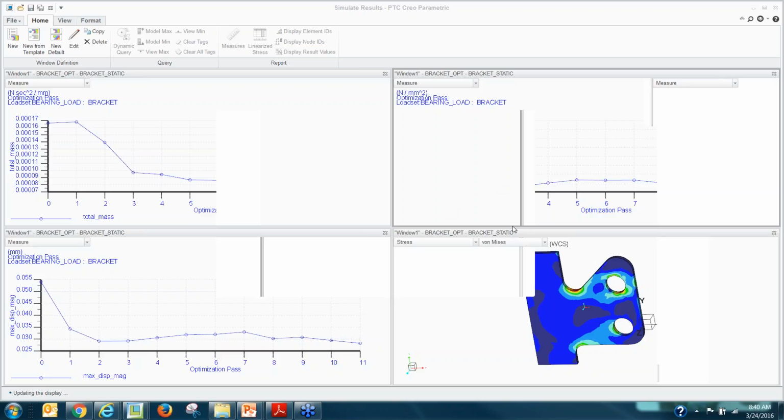If you have a structural resin with fibers in the mold resin, depending upon the mold flow, the fibers may align or not, and then would have different structural properties that influence the part's structural properties. Yes, absolutely. Can you simulate these directional properties of the molded part? Yes, you can. Remember I was going over the comparisons and capabilities in Advanced Simulate. There is a way to apply direction-based properties.